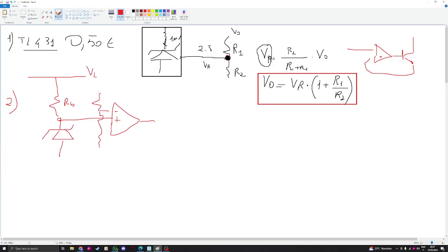Basically this is cheap. The cost of this guy is around 1 cent. You have fixed voltages, 6.2, 5.6, something like that. But there is a problem. It has a brutal drift in temperature. So the voltage reference will increase with temperature, and that is not good. So it is a cheap solution, but in some applications it might not be recommended.